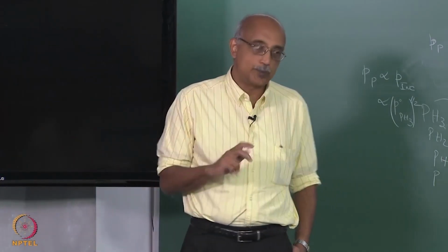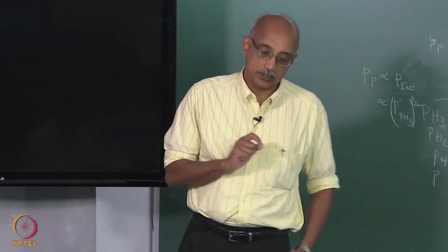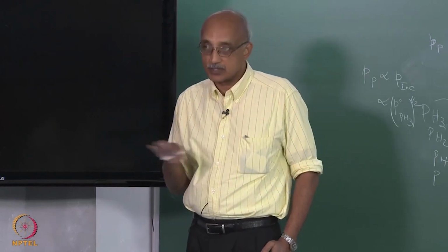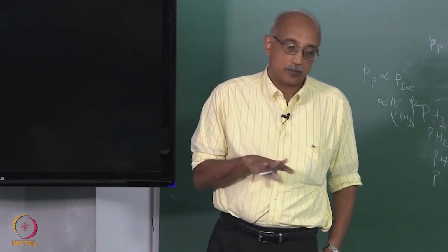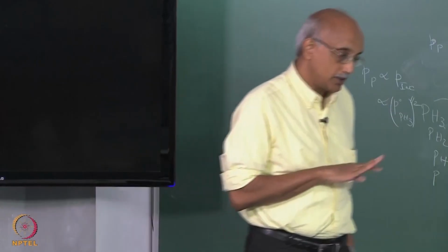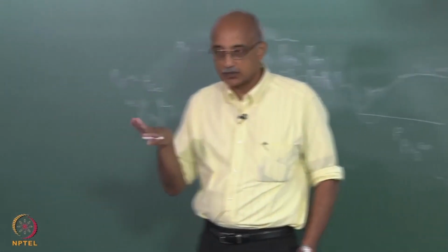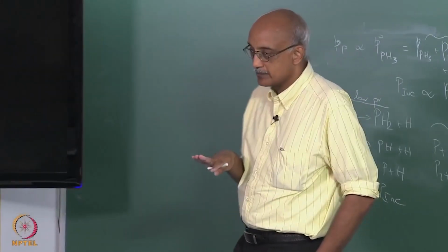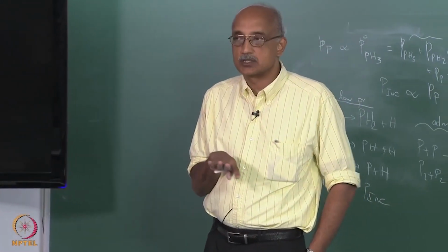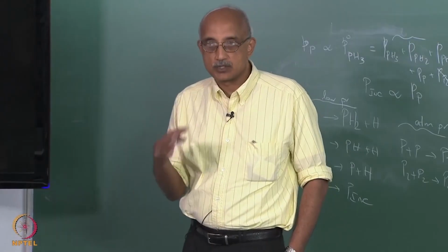In other words, the dopants have a strong influence on the roughness of the CVD film, and that is important to capture because the surface characteristic of a CVD film also has an influence on the sticking coefficient.